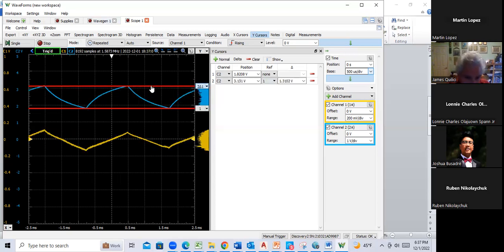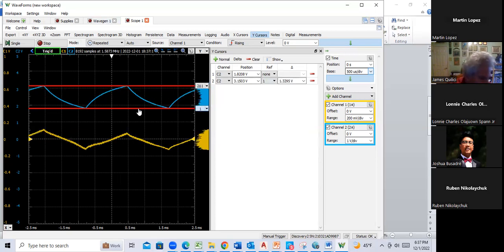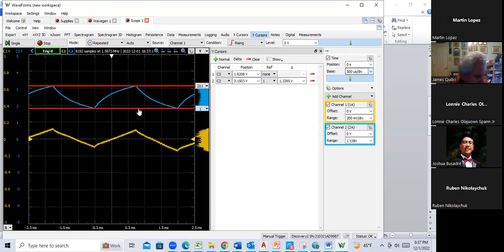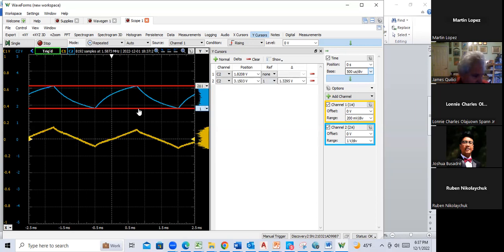I mean, you can sit there and dink around with the placement of the bars, but that's essentially where its 3 dB point is, somewhere close to 400 hertz. So yeah, capture that and then go back and look at what your SPICE told you and see if there's any correlation. Comment if they agree or not.